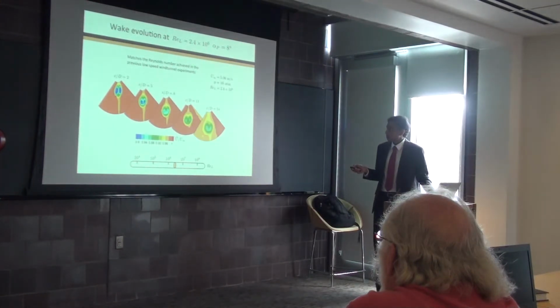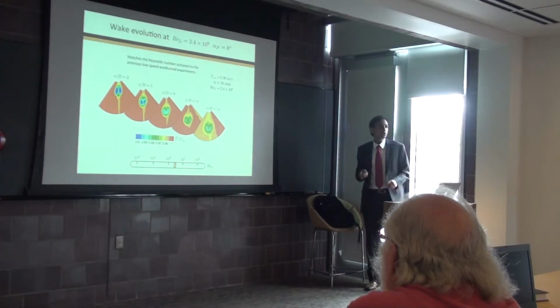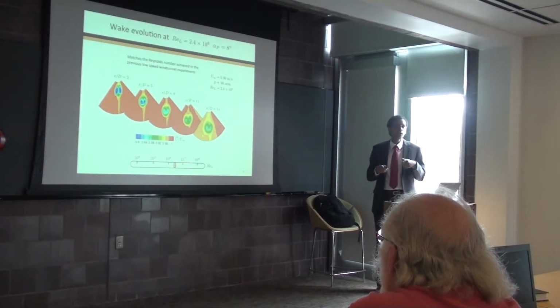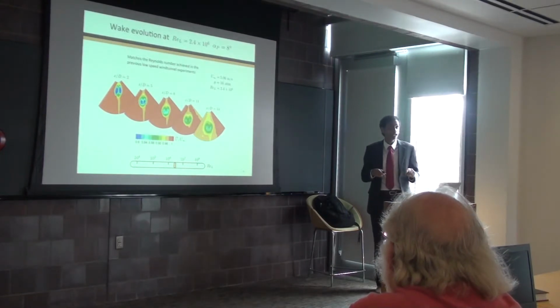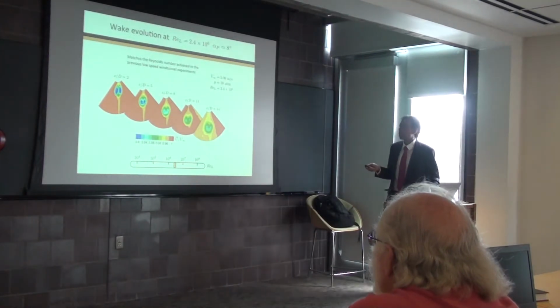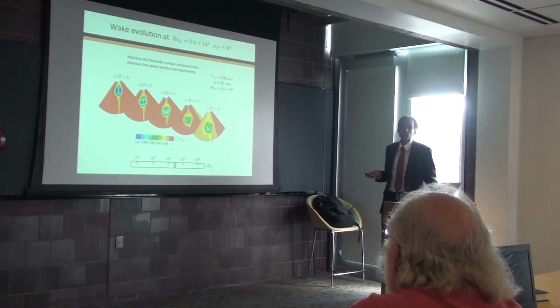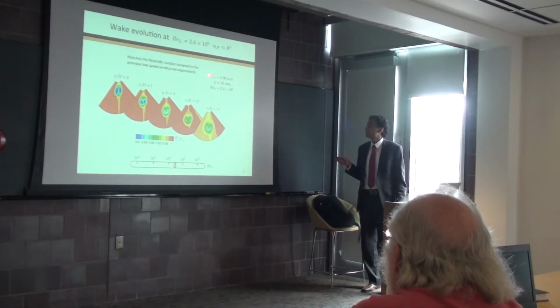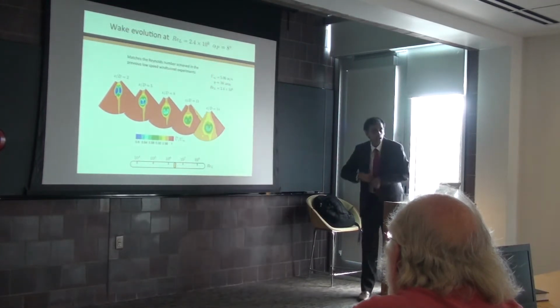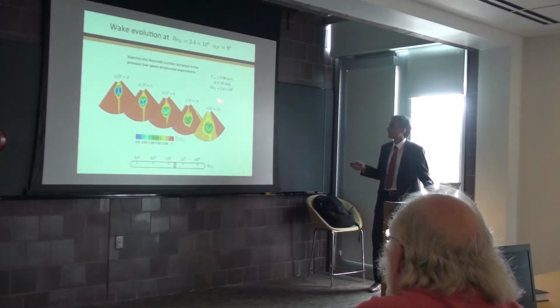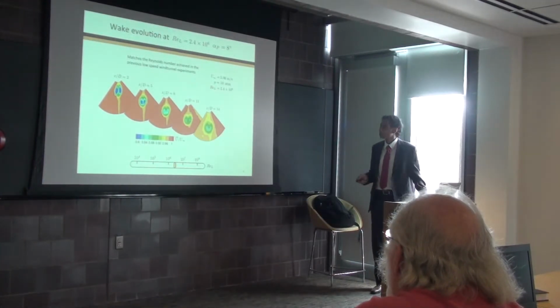The experimentalists in the audience will be a little worried here because I'm showing the 2.4 million case again. And as every good experimentalist knows, you never take data more than once in any case. So I've done that here, and this matches the Reynolds number achieved in the previous low-speed wind tunnel experiment. How have I achieved that? Keeping the free stream velocity approximately constant, pumping up the pressure from 1 atmosphere to 16 atmospheres, and this allows us to achieve that same Reynolds number.